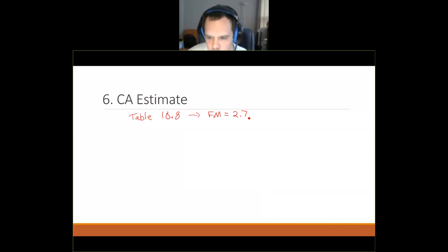Now, I'm looking at the table. You can look this up later, but the table value here is a coarse aggregate fraction of 0.73. I'm going to linearly interpolate the 2.7. On the table, it goes from 2.6 to 2.8, so you just linearly interpolate, and it's really straightforward to do when I pick nice round numbers like 2.7. And so this is my coarse aggregate fraction.